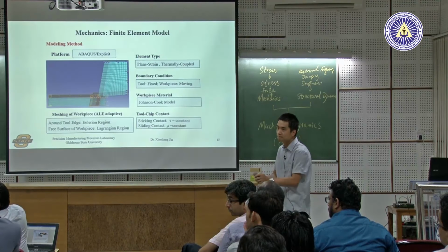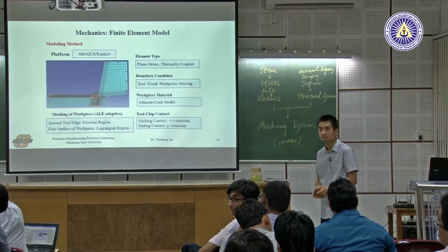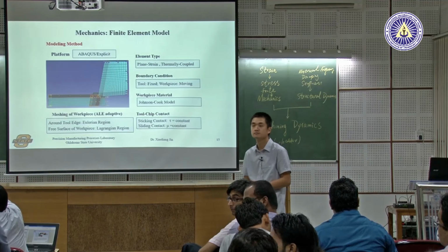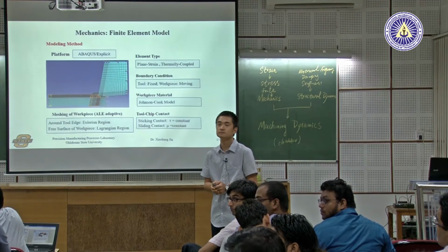In general, for fluid mechanics problems, people use Euler because the fluid flows and the mesh will not change at all. In solids, people mostly use Lagrangian because they need to see the deformation. But here, since the chip shape is coming, he uses Lagrangian in the chip, and only in the contact area, where the deformation is severe, does he want to avoid element breakage. There the elements will be fixed, whatever shape they have.